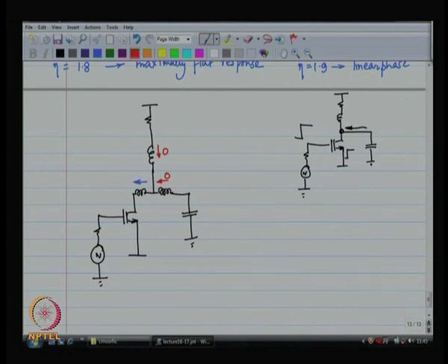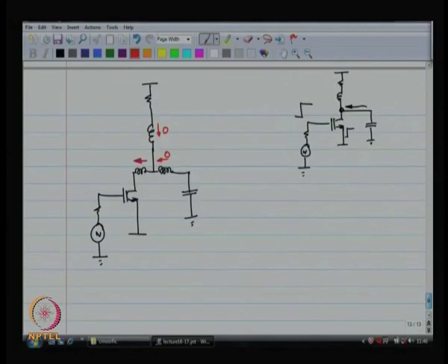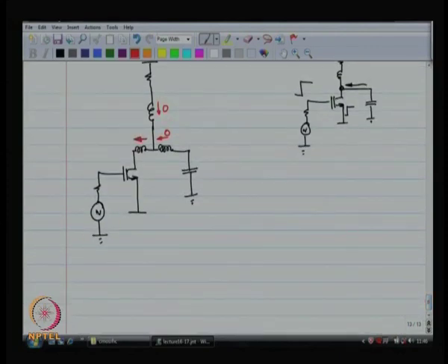Okay. And then when the current starts flowing through the second inductor, which one is it going to choose? Is it going to choose to come through the inductor capacitor series or the inductor resistor series? It is going to choose the inductor capacitor series, because at the right frequency the inductor and the capacitor together look like a short circuit. Okay. So, that is what you have achieved over here. Right. So, this particular circuit gives really good performance. Combination of these three inductors could also be modeled as a transformer.